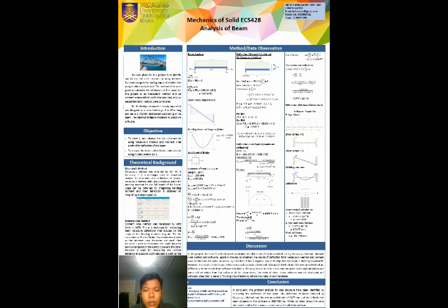In conclusion, the problem analysis for the real structure has been identified by calculating the deflection of the beam. The deflection of beam obtained by Macaulay's method and moment area method is 0.7477 millimeter, and the deflection of beam obtained in the software is negative 930.766 millimeter. While for the shear stress, the value obtained is 1148.4 kilonewton in manual calculation and 1148 kilonewton in software.